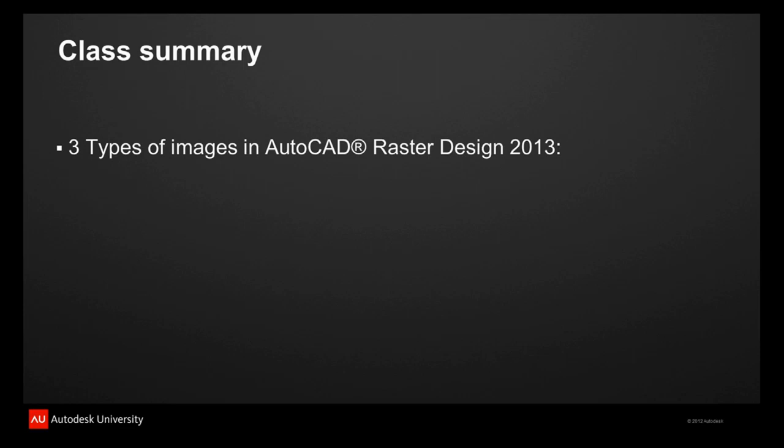But you've also got an interface. So once it recognizes the text, you can still go and edit that text. So instead of retyping everything, it skips a few steps. It does a few steps for you. It firstly removes the area of where the raster text originally was. It tries to identify it as closely as possible. You can then quickly make a change if you want and click on OK, and there it is. Alternatively, remove the region where this text was and put in M-text or single line text. Character by character to make sure I got it right. Yeah.